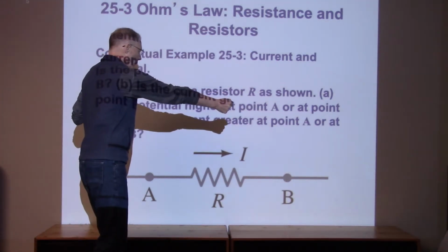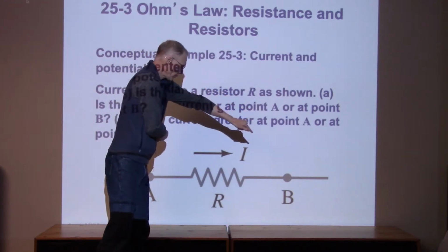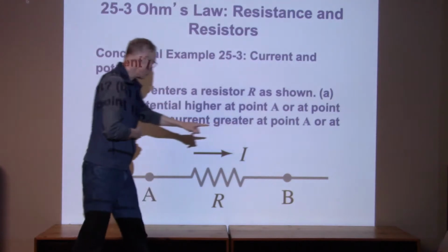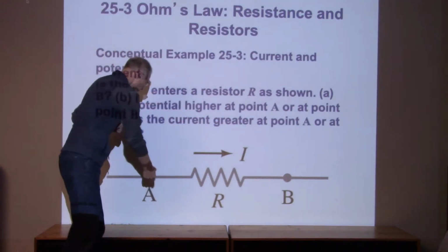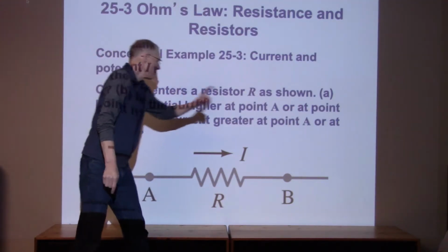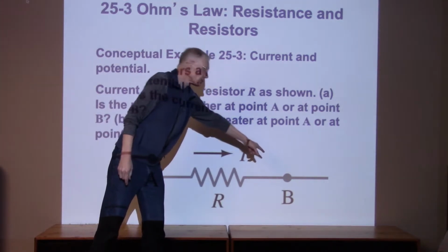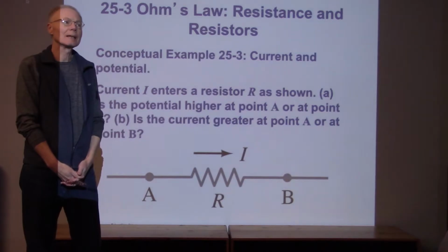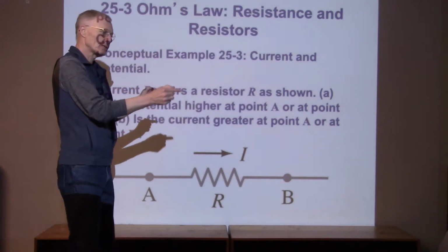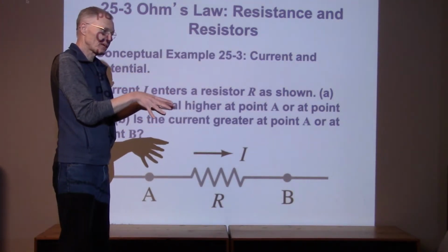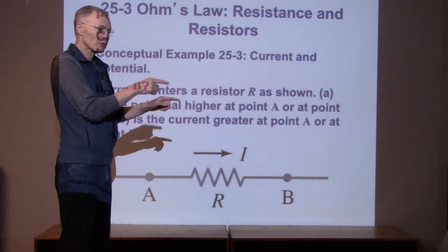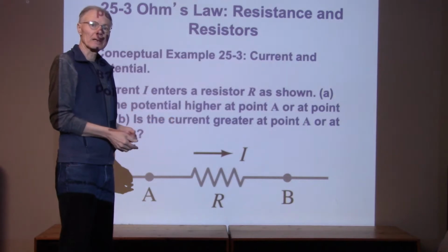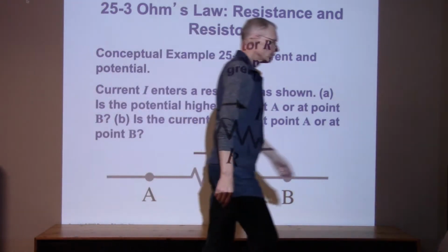If I now take the wires on my voltmeter and switch them, then what's happening is we're measuring B now relative to A. If I take that common line and connect it to A, B is going to be at a lower voltage, and now when I connect those wires, it'll tell me a negative value. And again, we saw that in lab. We saw if I've got the voltmeter set to DC, that switching the wires will change the sign, plus or minus, on the reading. All right.